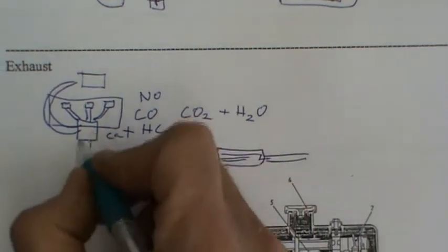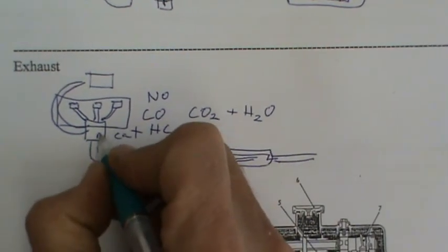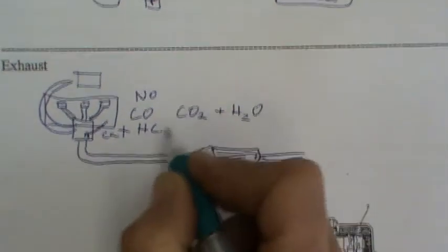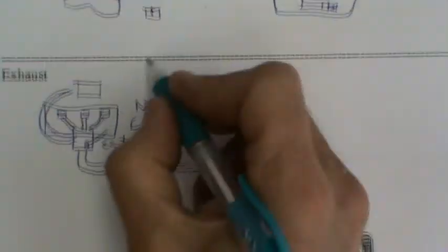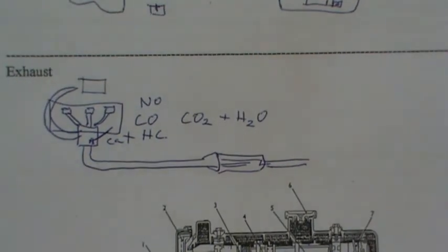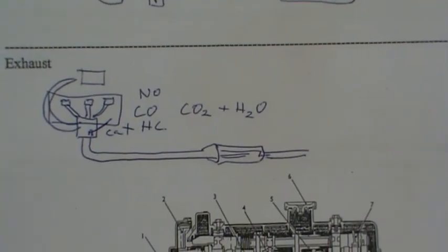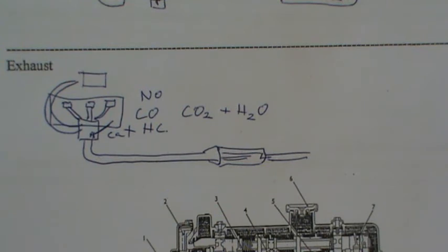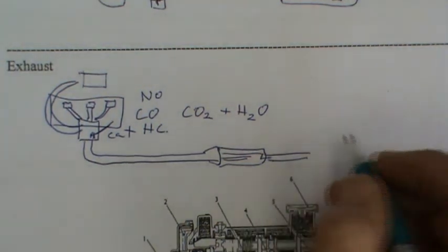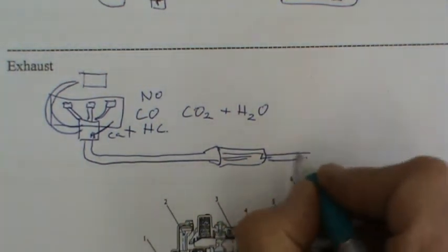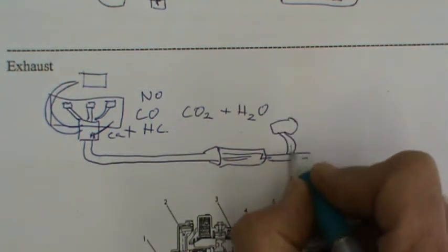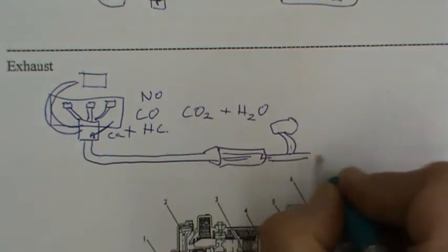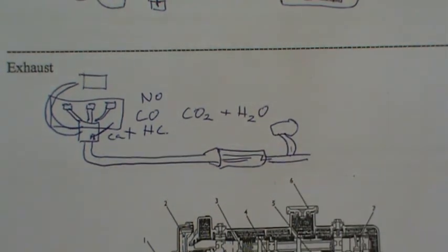You might have an oxygen sensor going off from your exhaust to your ECU, the engine control unit. And there might be air injection too. Some vehicles, to lower their emissions, just pump air from an air pump in so that there's more air in the exhaust so that they pass emission control systems.